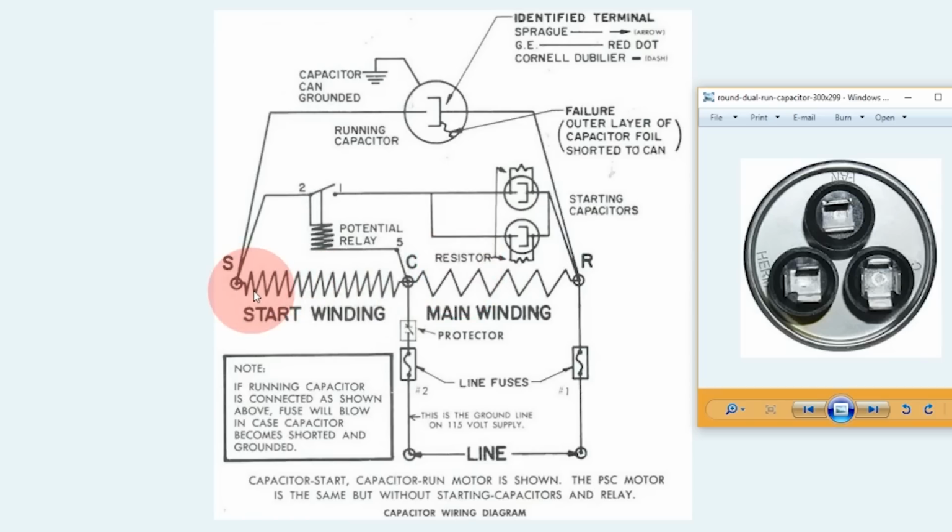It's back electromotive force. Your motor actually acts like a generator as well and generates a higher voltage. But again, the highest voltage that your motor is going to generate is when it's up to full speed. That's not going to be during starting. And many of the failures attributed to a capacitor come when people say, well, when the motor has a hard time starting or when the system's short cycling, then that causes your running capacitor to fail.